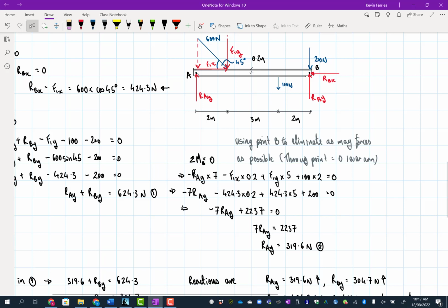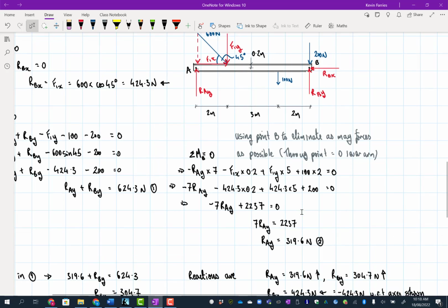And so then I rethought, oh, I forgot that this one I put down as positive, but actually it's going clockwise with this direction. Therefore, I need to make sure I'm writing down that moment as negative. Okay, and then I've just figured out, so we've got this force here has a moment, this force here has a moment, just being careful whether they're clockwise or anti-clockwise about the point B. I'm doing everything about the point B, and I've worked through and got my answer there.